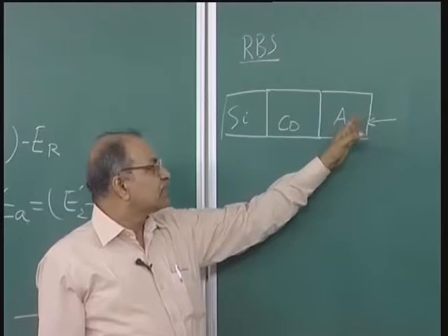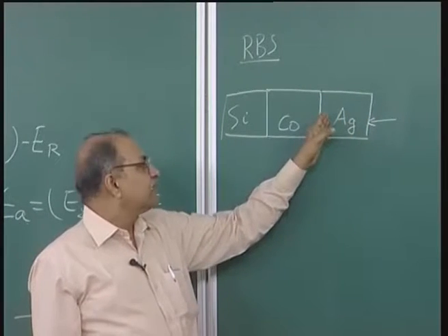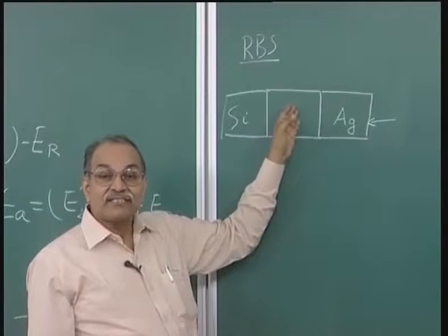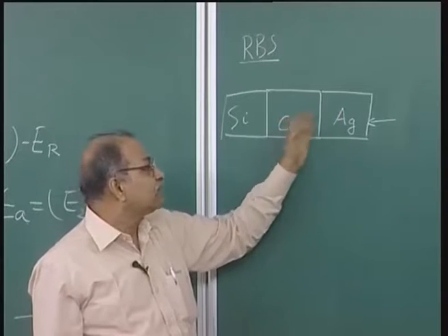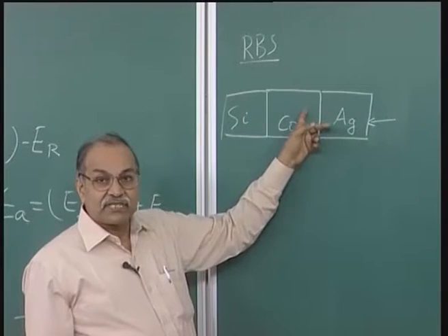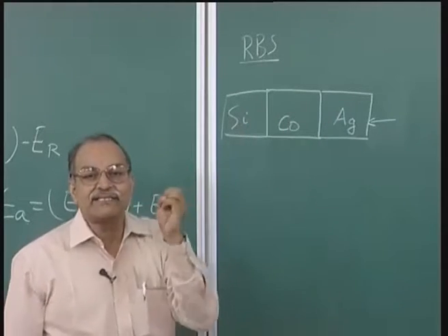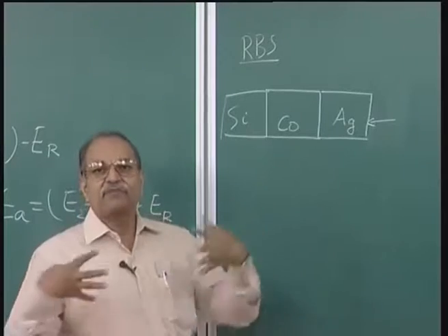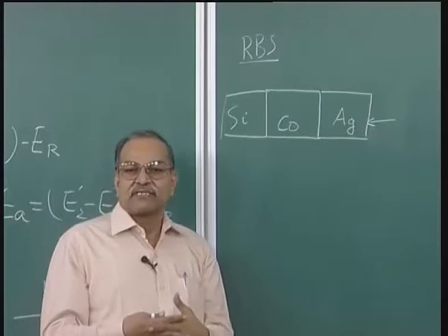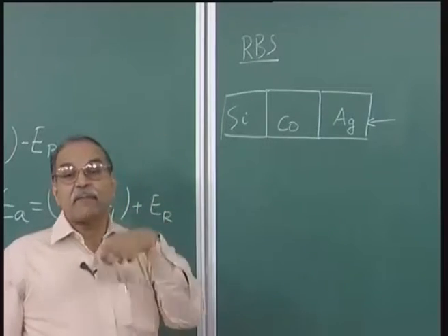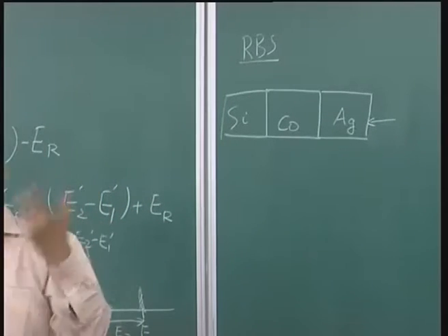If it is pure silver, it is the same concentration, and then cobalt the same concentration, but at the interface there will be diffusion. Cobalt will come this side, silver will go that side, and many of the physical properties will very sensitively depend on how sharp or how diffuse the interface is, how much mixing there is, or deliberately people do mixing to make different phases.